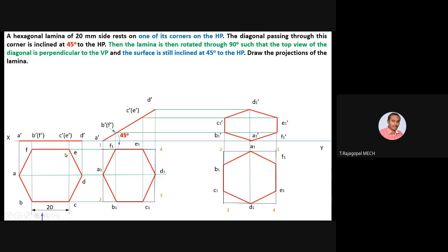You see the difference between H and 2H. Only the boundary related to the hexagon, the object outline, is in thick line. All the remaining projectors we are extending for our purpose, including this rectangle, should be in thin line drawn with 2H.